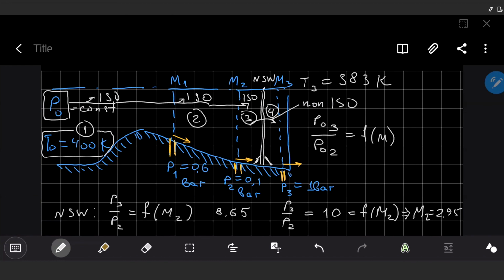There is no significant change in the computational part. It would just look similar to what you would receive, for example, in a numerical simulation of your nozzle. So you will not be confused why you have a very straight shock wave in the book, and when you are simulating you have a lambda shape of the real shock wave.